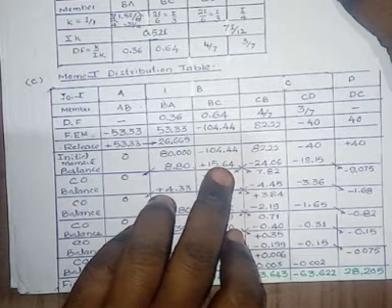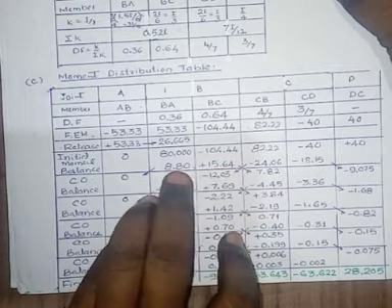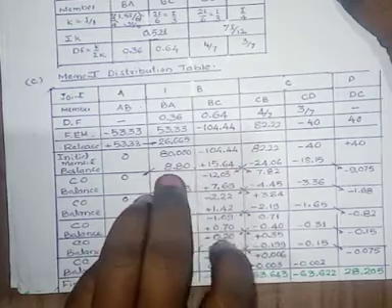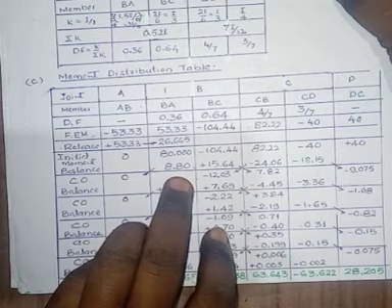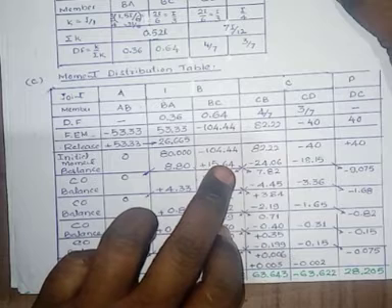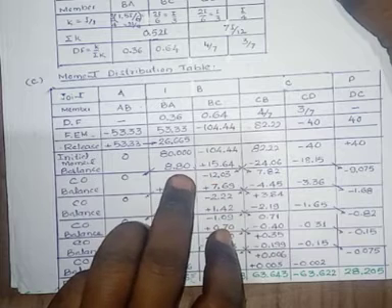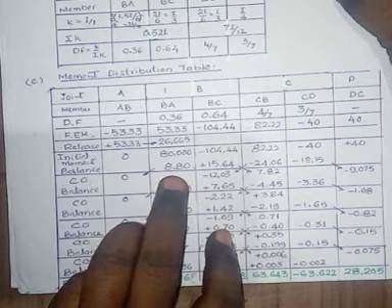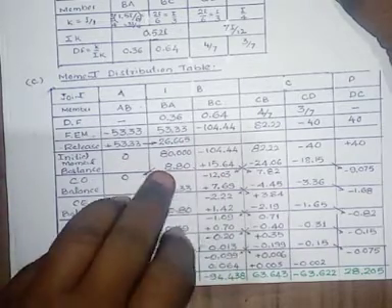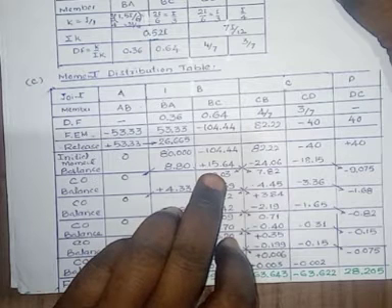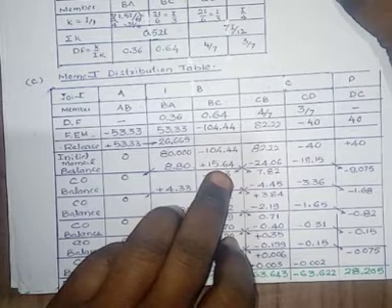You know that at a joint, when the equilibrium condition is reached, the summation of the moments at that joint is 0. Here now it is unbalanced. We have to make it balance, that is balancing. That one is 24.44. 80 minus 104.44, that is minus 24.44. We have to add plus 24.44 to make it balance, that is plus 24.44 into 0.36, that is 8.8. That is for BA. 24.44 into 0.64, that one is 15.64 for BC.